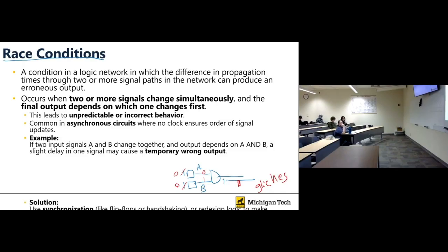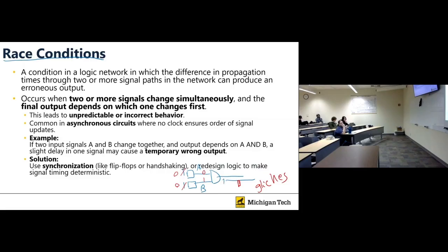Using handshaking is one of them. Instead of using a clock, we find another way to synchronize. That's how the general approach works: find another way, instead of a clock, like acknowledgements. Send a request and acknowledgement. That's one of the general ways. But based on the system, you might have different methods. I will check to see if there is a more general way.